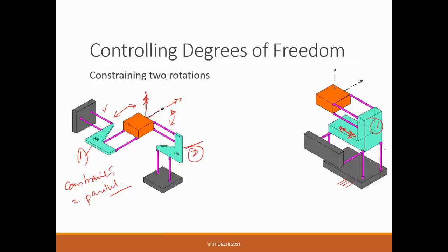If you see, there are 3 and 2. So along this axis, it can move. The translation it will have. Now you want to connect them further so that you get only these 2 constraints, and you get rid of other constraints, right? So you have only one translation and 5 constraints from here to here, 5 constraints. Ultimately, you want to go towards 2 constraint systems. So you remove other 3 constraints also.